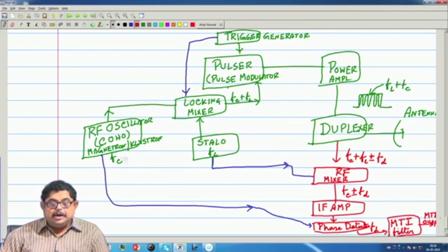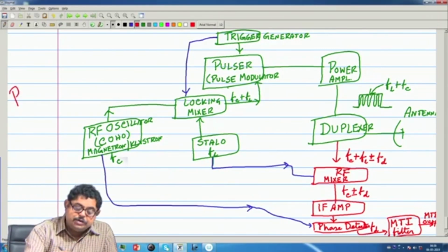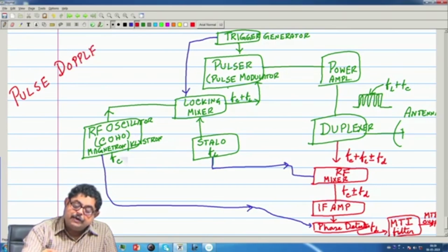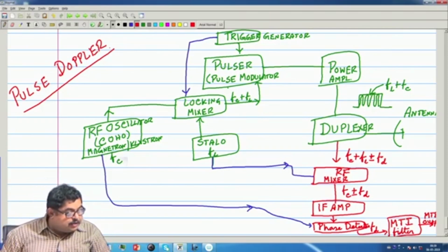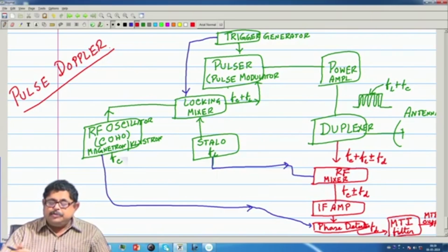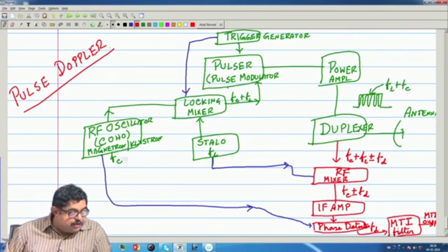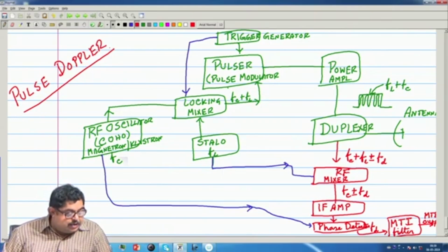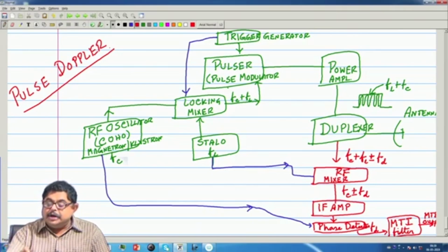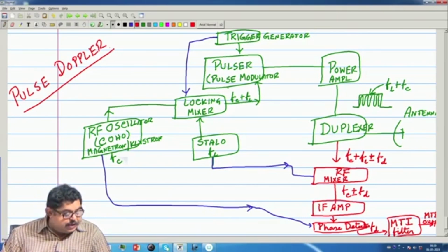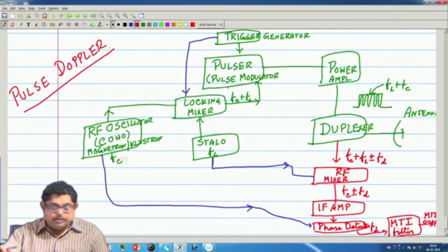Okay. So, this is the typical block diagram of a pulsed radar. I should say basically an MTI filter type of pulse radar. Pulse Doppler is a different thing. So, I can briefly summarize what I have said: in any pulse radar the transmitter is turned on and off by the modulator at a fixed rate and for a fixed duration.